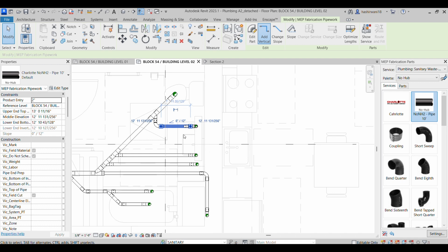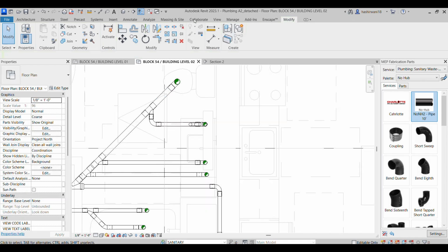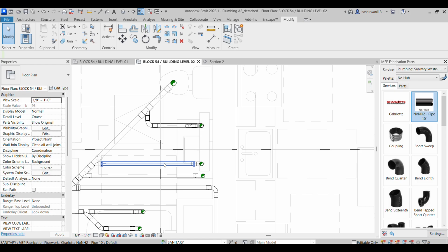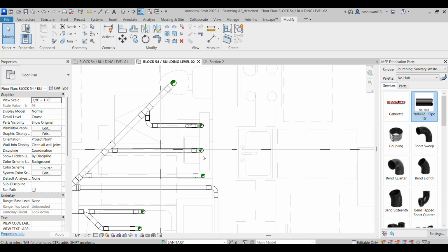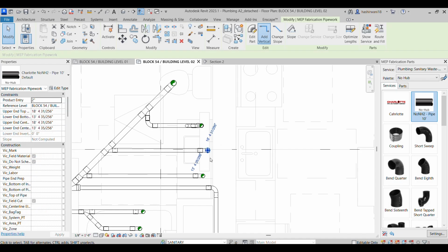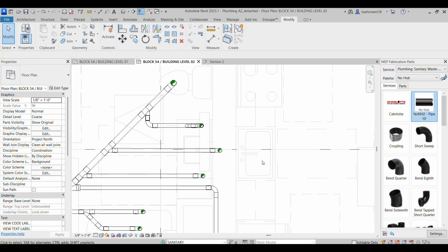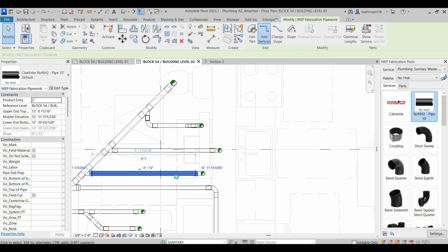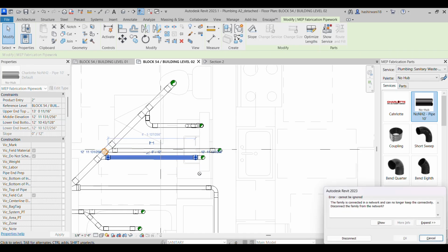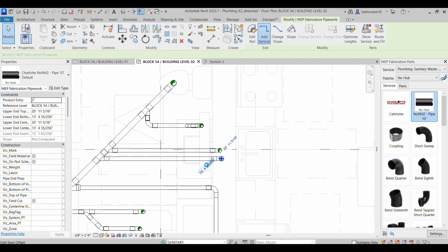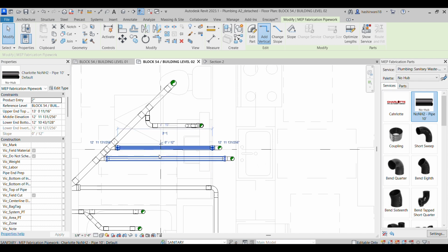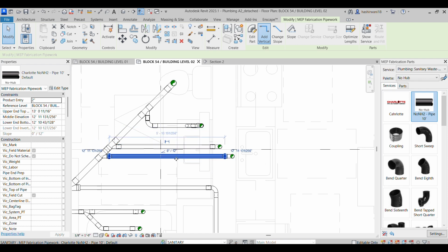So I'll just go here. So this is the vent pipe, right? What I'll do is try to align this with the middle of the sink here, and then I'll try to move it into the wall, because this will all go into the wall. And then for this we have the sink in the other room. I won't be able to get too close. Simply select it and go across up until here. I'll move it a little bit up, and then this one, okay.